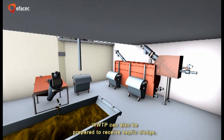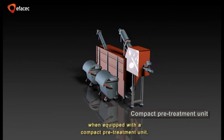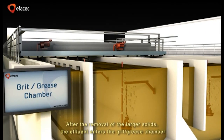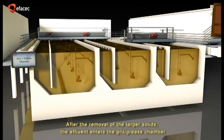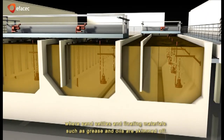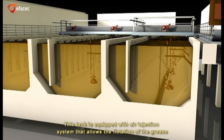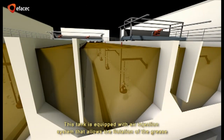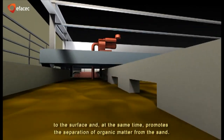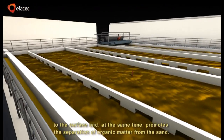WWTP can also be prepared to receive septic sludge when equipped with a compact pre-treatment unit. After the removal of the larger solids, the effluent enters the grit, or grease chamber, where sand settles, and floating materials such as grease and oils are skimmed off. This tank is equipped with an air injection system that allows the flotation of the grease to the surface and, at the same time, promotes the separation of organic matter from the sand.